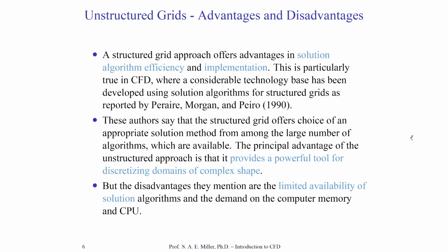I can have a single fluid domain or single mesh that represents very complicated geometry, as I'm simply triangulating the surface of these complicated shapes, which can then be connected to the volumetric part of the unstructured domain. Of course, the major disadvantages are that it is much more difficult algorithmically to create an unstructured mesh, and we'll look at those algorithms in a few minutes. The other major disadvantage of the unstructured approach is the increased use of computer memory. One should expect, for the same problem, to use more memory on a grid point basis and solver basis for an unstructured approach than an equivalent structured approach.